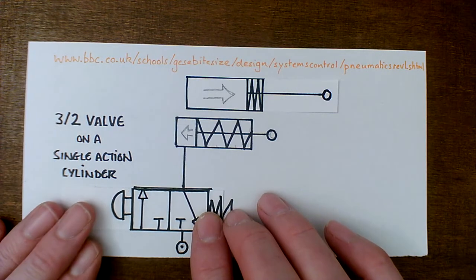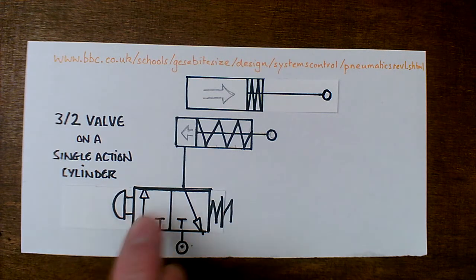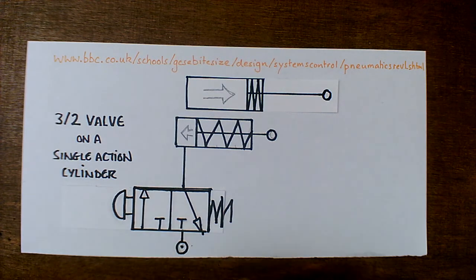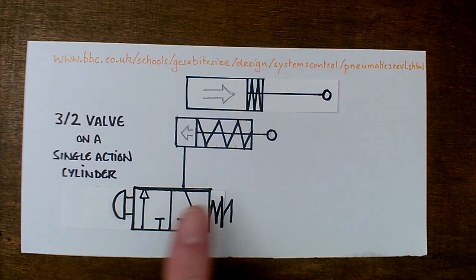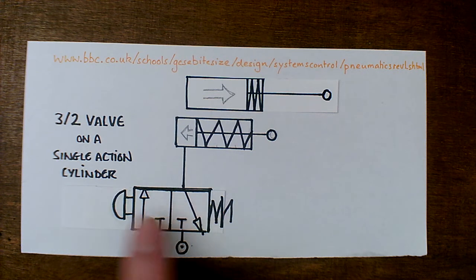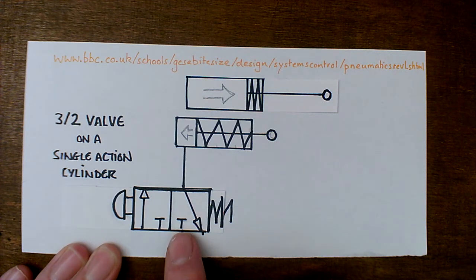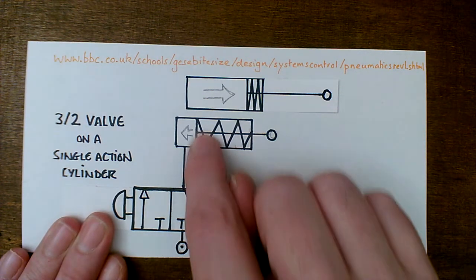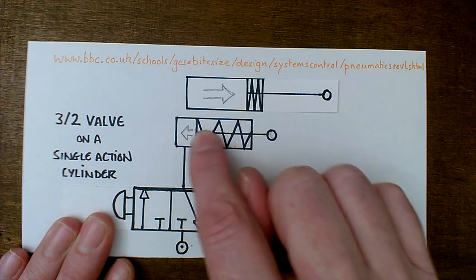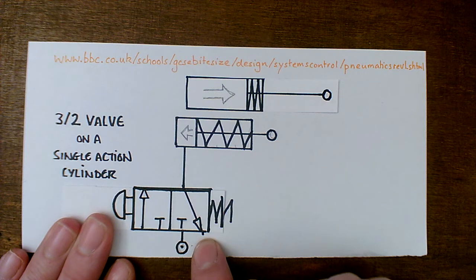These diagrams look really complicated, and it's because you see this section here that's not connected to anything. Well, actually, to understand these diagrams, you need to use your imagination, and you need to be able to visualize this part actually moving, because this and this are part of the valve. So here's how it works. This symbol here means air in. So there's air going into this tube here, and it's reaching this T block, so the air is not going anywhere. You can see here this spring is pushing back against this flat plate. This is inside a cylinder. It's a bit like a bicycle pump. So the air is able to pass out through here and to pass out through this exhaust port.